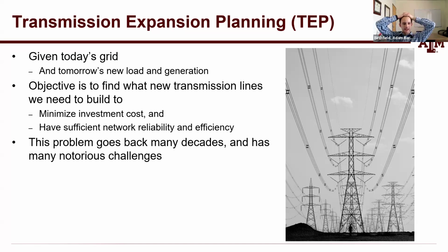Okay, there's a question about the validation metrics and to what extent they turn out to be useful and consistent across different regions, and to what extent they would be more specific to a single region. I can give a few examples. One very surprising example was degree distribution. Degree distribution is the average number of transmission lines connected to any particular node. And there's actually a wide disagreement in the literature about degree distribution.